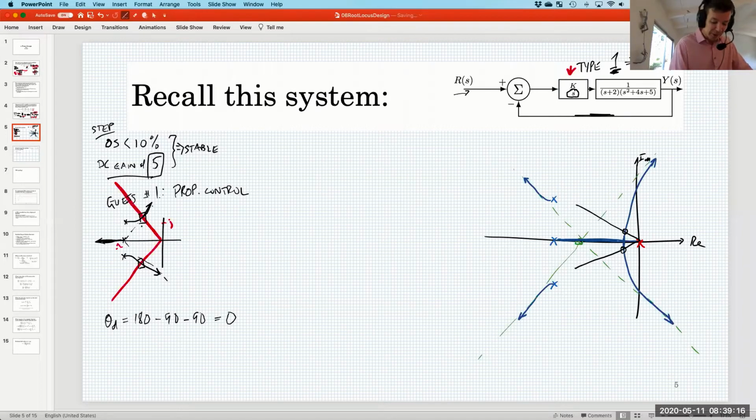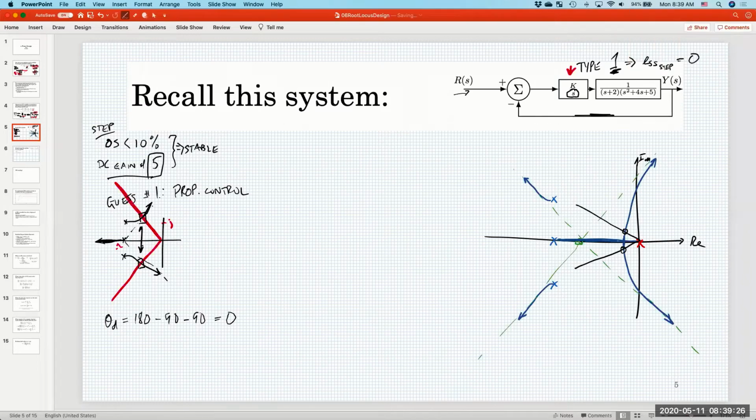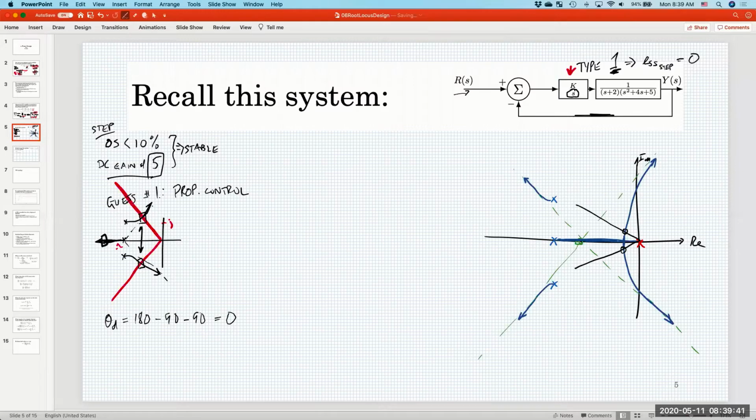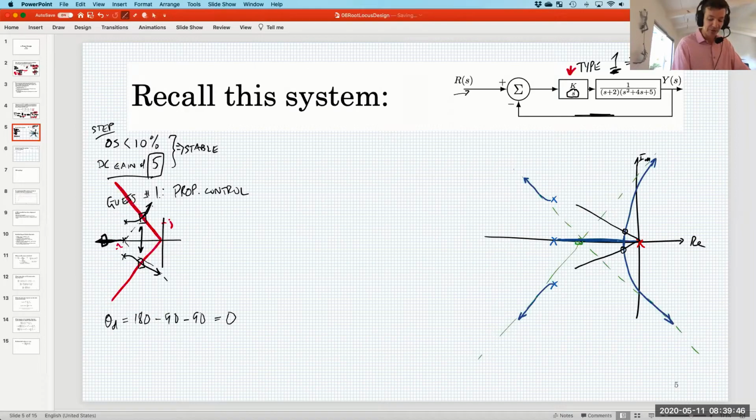Is it reasonable to expect that these two closed loop poles will dominate? Is that even a sensible question to ask? What do you think? No. They'll dominate more the further to the right it goes, but the system is wanting it to be further to the left. So nothing about our requirements actually requires us to go further to the left. Within the cone, though, I meant. Sorry, within the cone there is this tension that to get these two poles to dominate, we would have to increase the gain, which might send them outside the design cone.